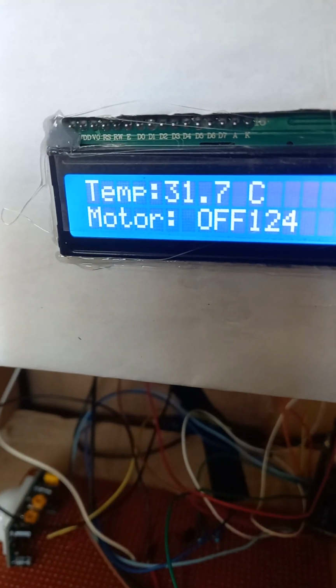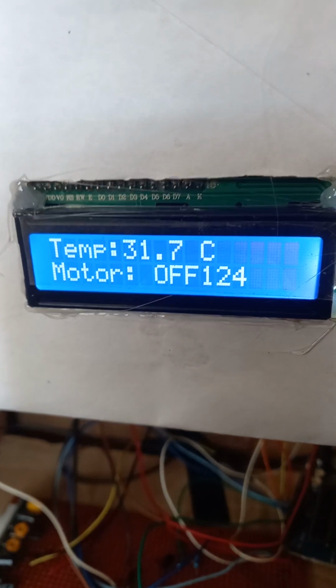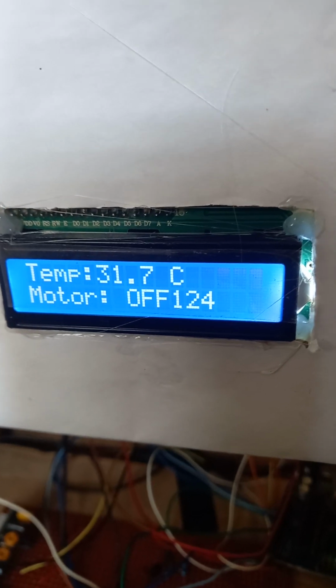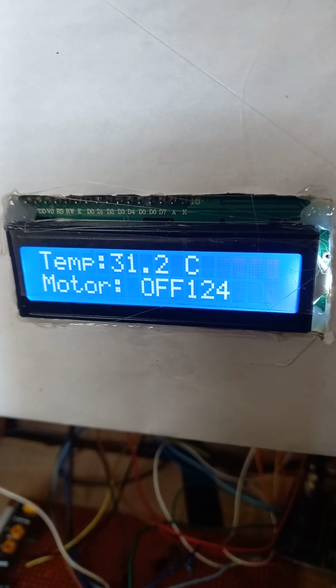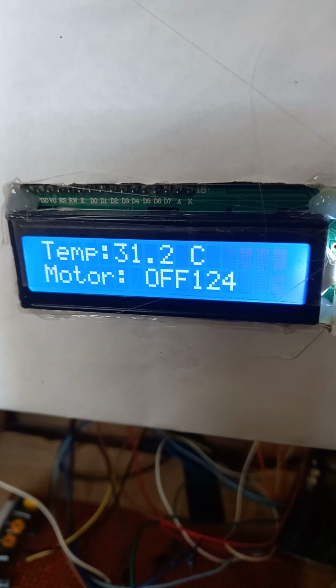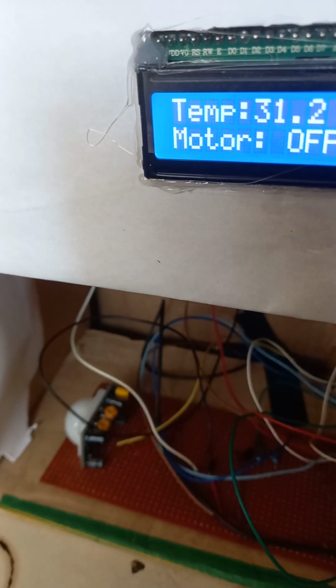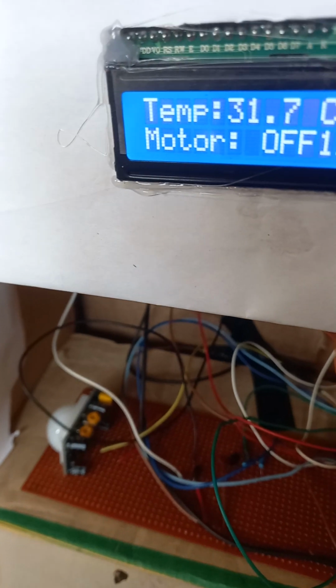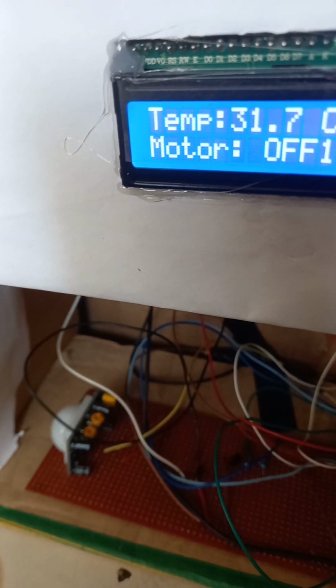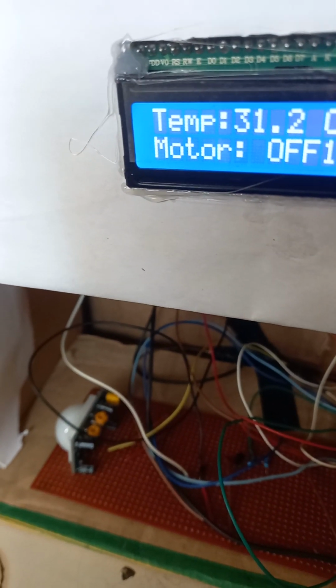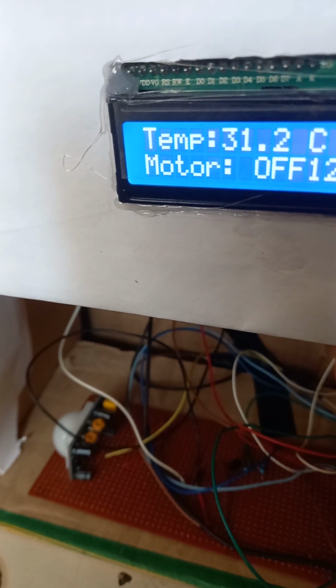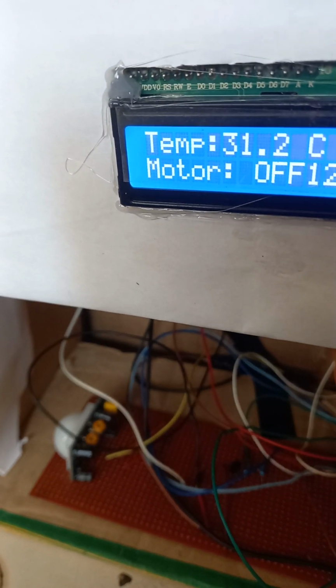So now the motor state is off. We want to turn it on, and to ensure that our sensor is working, note that it only detects a human being or an animal. That's how a passive infrared sensor works. It cannot detect obstacles from other objects.